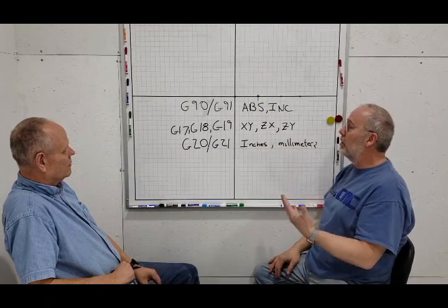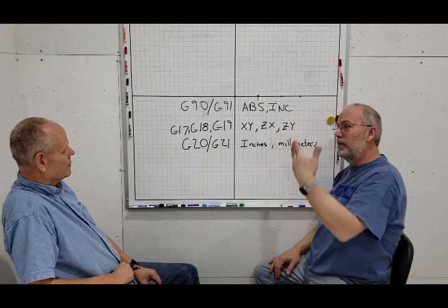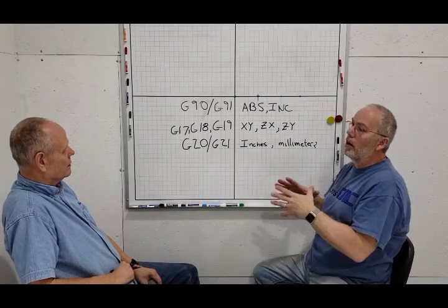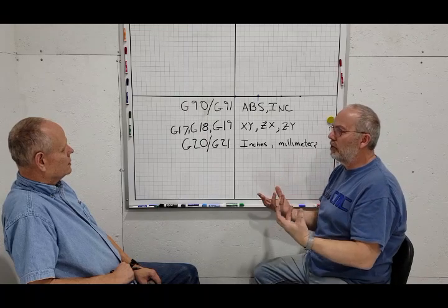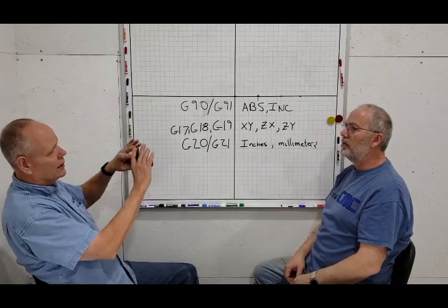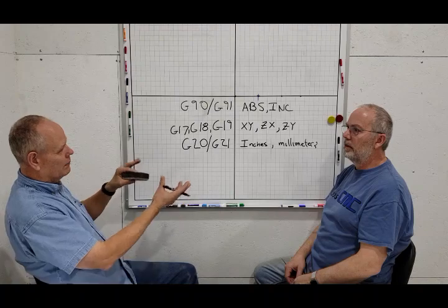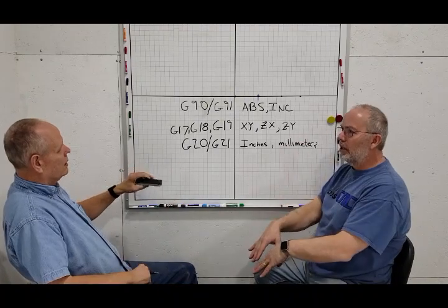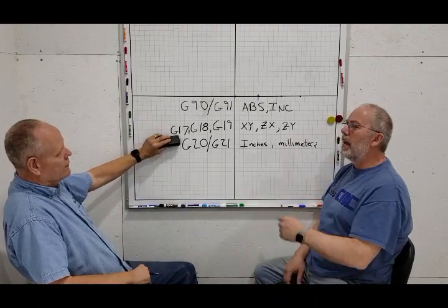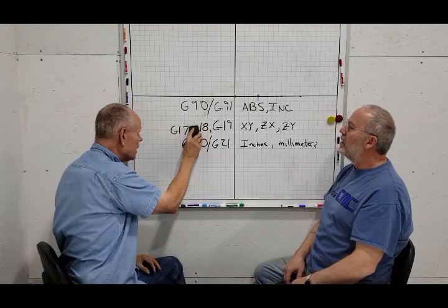Your Z now would actually have, your spindle would need to be rotated sideways, or your machine configuration would be different. Unless you're industrial, this is the only thing I gotta care about. If you see a G17, I'm milling something, I'm making my life easy.